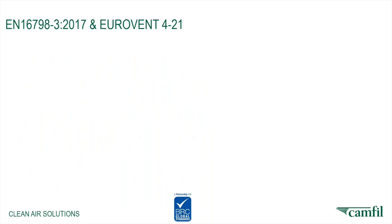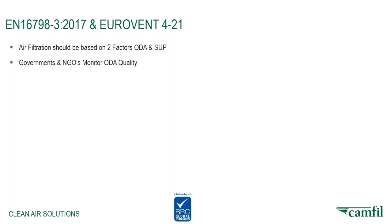So what we're going to look at now is EN 16798 and Eurovent 4/21. As we discussed earlier, air filtration should be based on two factors: outdoor air and supply air. Governments and NGOs monitor outdoor air quality, and as we've seen in the previous slide, the outdoor air can be ascertained by checking these types of website and databases. Food and beverage facilities are specifically referenced within EN 16798.